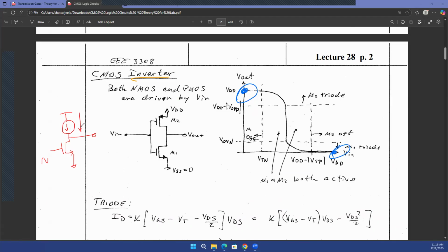So analog circuits are static circuits. They continuously draw current. In digital circuits, only if your input switches, you have that switching behavior for the transistors, and then you consume energy during the switching. If you're not switching, you do not consume energy. That is one benefit of the digital circuit, that if the switching rate is very, very small, the power consumption can be made very, very small. Questions?